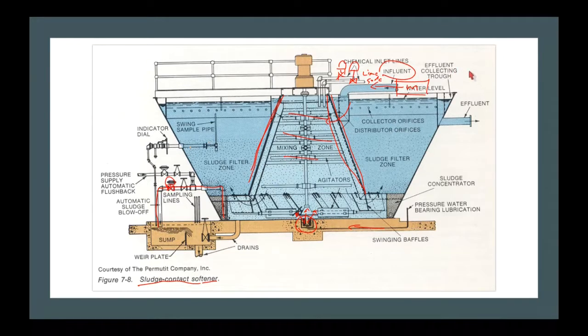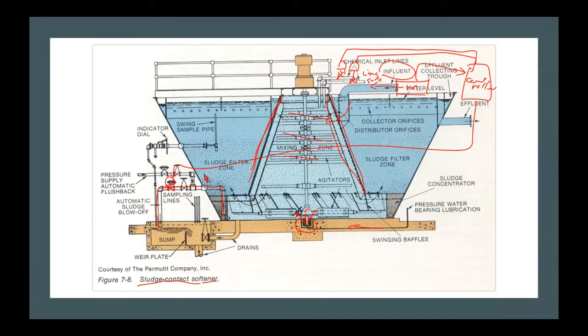And so what we have is a brain, a controller that looks at the water flow. Okay, there's our controller, so water flow, and then it's going to send out control signals to the various control valves so that blow-off, chemical feed, all of this stuff is related to two things, the water chemistry and the actual influent flow.